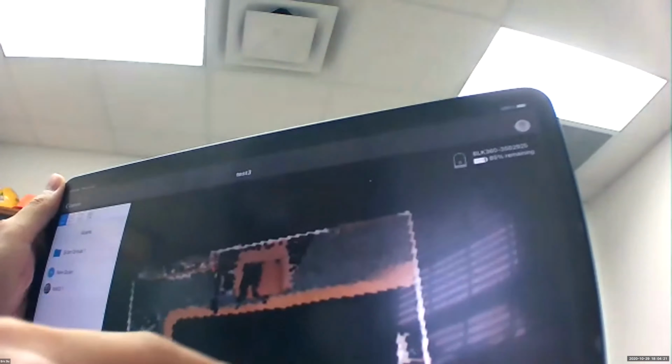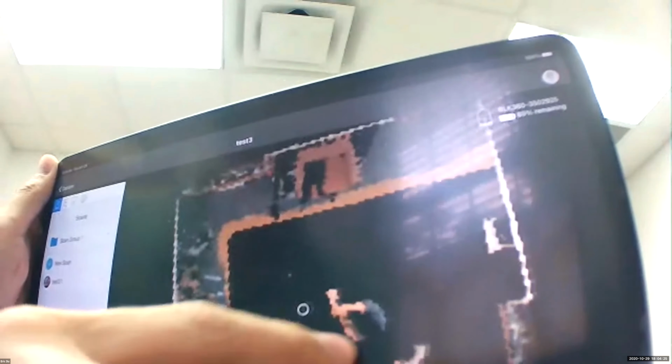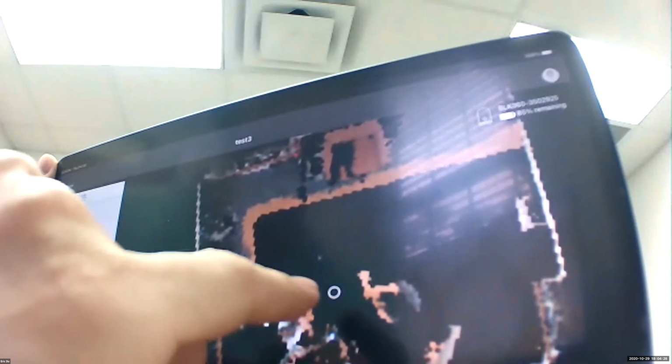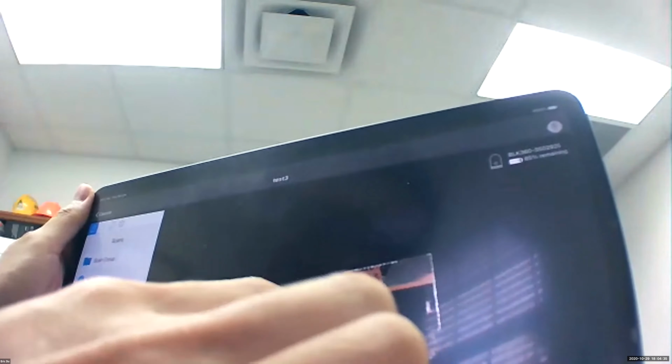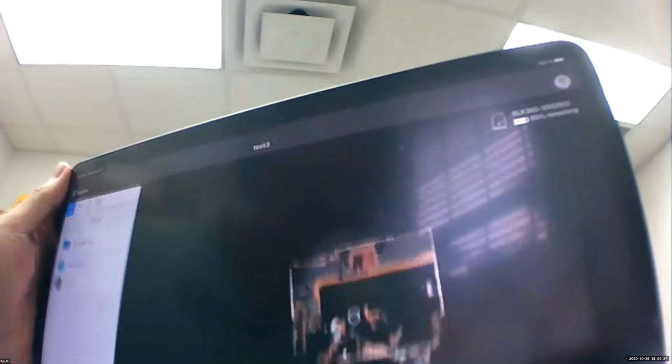So this is my office where I'm teaching you guys. Now I'll show this map view, and I don't know if you can see, this is the layout, the floor plan of my office. It already generated that, and documented the location of my scanner, and the scan model here. Okay, so one scan is not enough, because number one, you don't have enough data points with just one scan, and also number two, you are probably missing the information just nearby the scanner. So usually we need to do multiple scans.